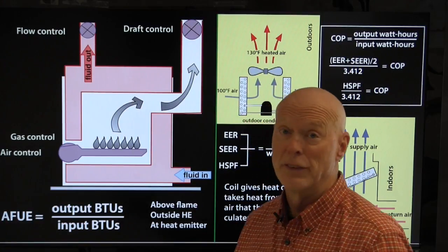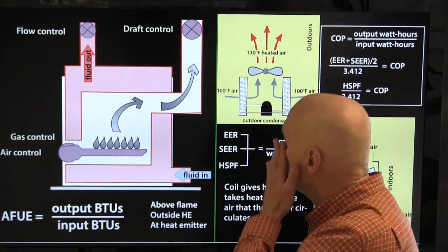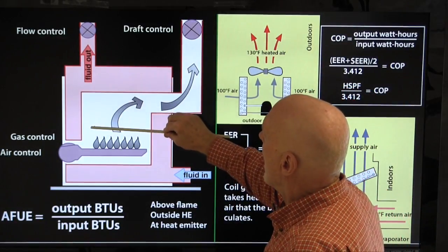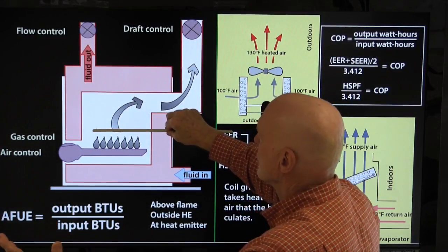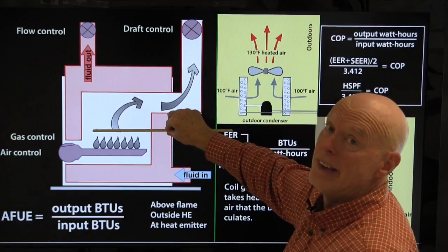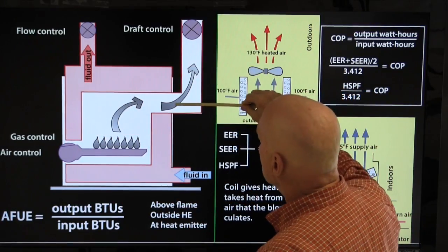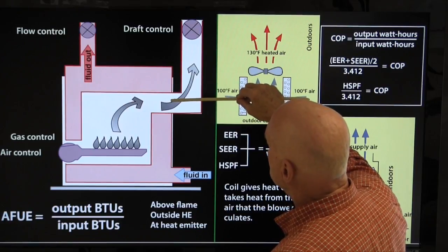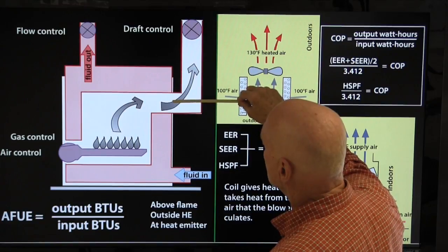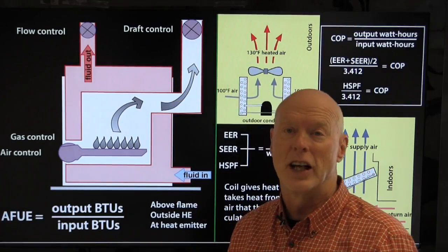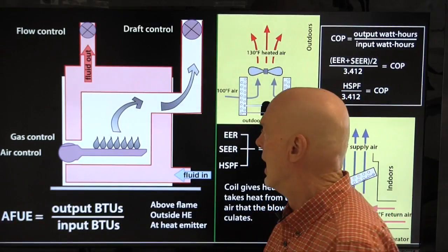And there are a number of different efficiencies. The AFUE is only one of them. We could measure the efficiency of the gas burning, and it's probably something like beyond 99.5. We could measure that right here, but if we measure the wasted heat right here and calculate the efficiency from that, that's called the steady state efficiency, and we can do that with a combustion analyzer.